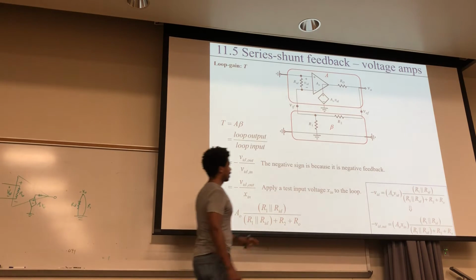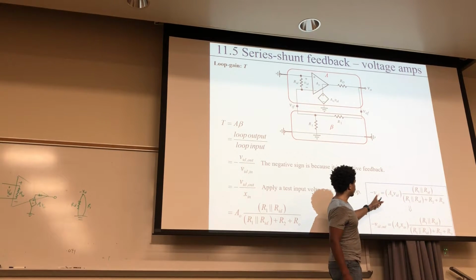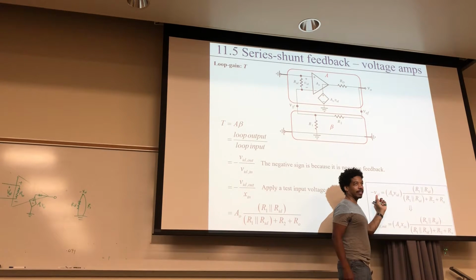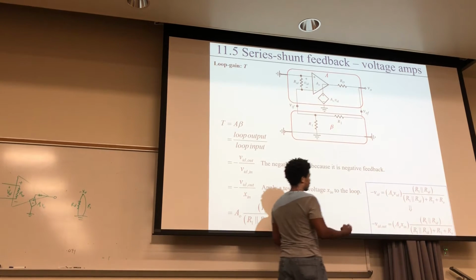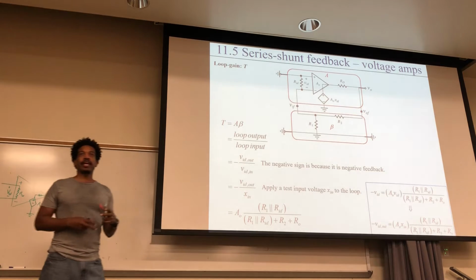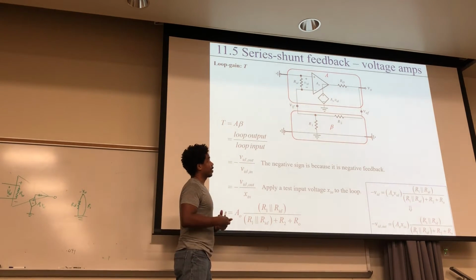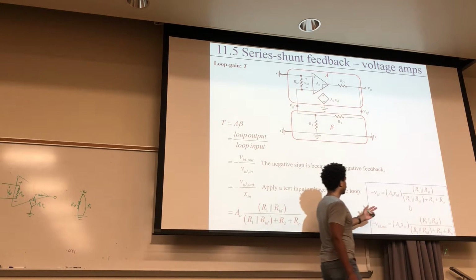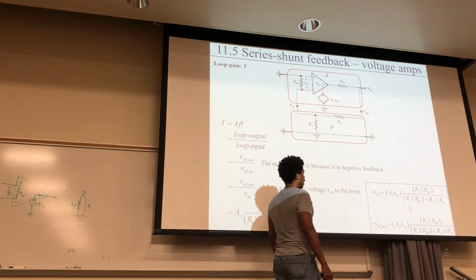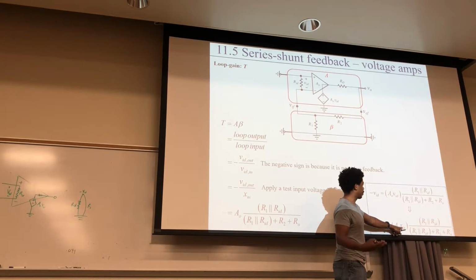So here's the equation from the last slide. We got this by voltage division. And what I'm doing is I'm looking for VID, because this is my output voltage right here. Here's my input voltage. Now I know you're saying, aren't they the same thing? Well, yeah, they are. But in this type of analysis, what you're trying to do is disable your feedback by taking control over it and assigning it a voltage. So it loses its ability to do true feedback, right? So you're taking over this, and then you're looking for this. So here's the unknown you're looking for, because that's your output, that's your input. And that's why I'm rewriting it like this, where I've taken my VID and replaced it with XIN, some kind of input voltage. It could be a number, like I said.